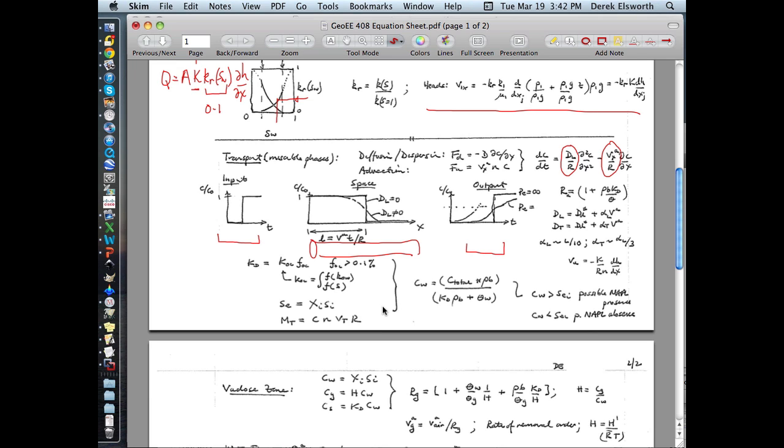And we defined them in terms of a couple of different parameters, I think. One was residence time, or non-dimensional residence time. One was a relative concentration, and one was a Peclet number, which, if it's not given here, Peclet number was what? A velocity times a length divided by dispersion. And this relative time, which I don't see on here, was equal to time.